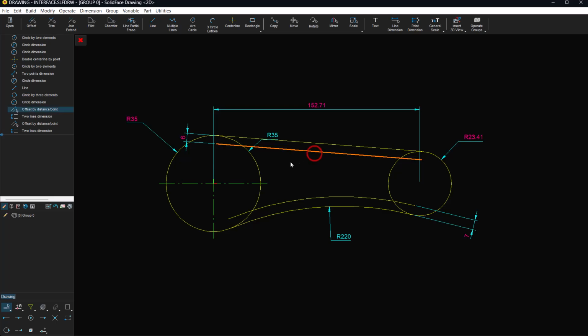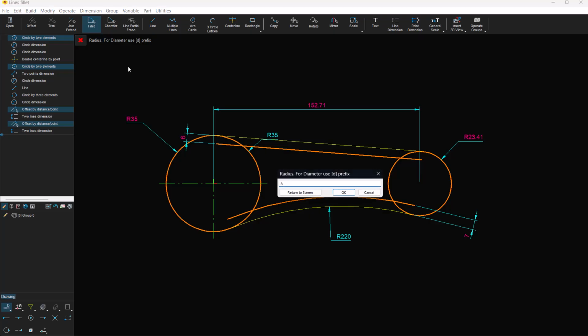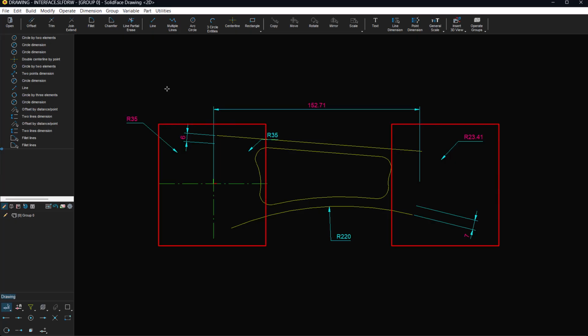Adding internal contour and fillets. Let's select the lines in sequence. Fillet of 8. See that the outer arches have been erased. The circle should have been separated at the tangency points before the fillet operation. At this point, we could continue and create an external arch. But let's undo the operation to return before the fillet operation.